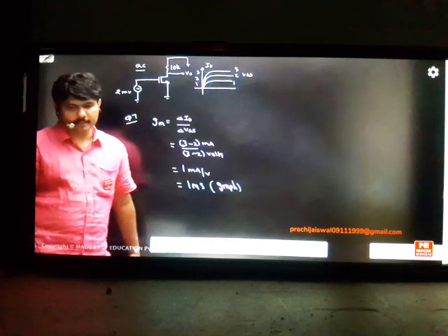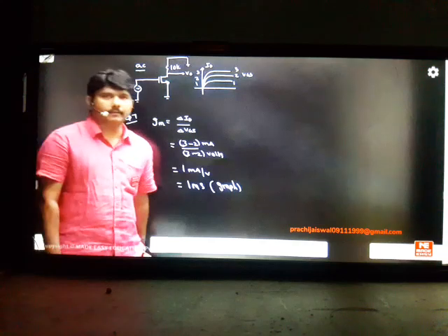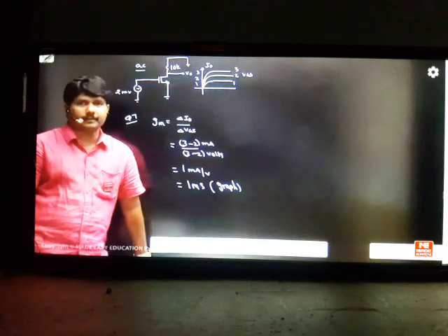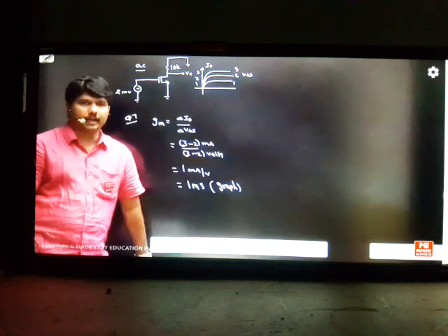Having a resistance in series won't affect the voltage gain. Yes, Partha, what you said is correct. Whenever they give a series resistance in MOSFET classes, the current is 0, so it will not impact your circuit. Only this impacts the current gain calculation. In the case of BJTs, the RS effect will be there.